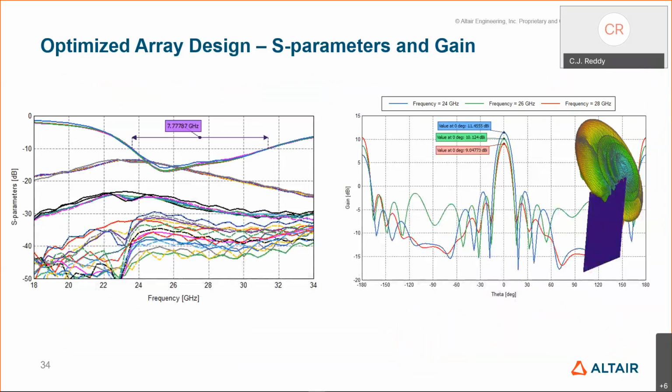So if you look at the design here, you can see all S parameters for the 8 elements. They are well below -10, around, I think the center frequency it says 7.7 gigahertz, but that's a bandwidth I guess we have here at 26 gigahertz as a center band.